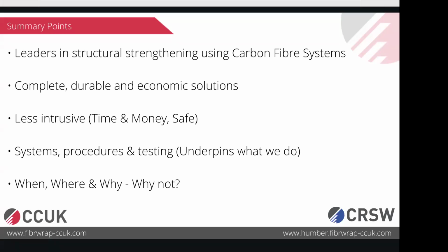The systems, procedures, and the testing. This is what Jayesh has said. If Jay gives my teams or our guys on site a design and it's not applied correctly, then you're going to have a problem. It's absolutely critical that the application process is followed, and this is why none of anything that we do is subcontracted out. It's all kept in-house. Our guys are with us for a minimum of 2 years before they're allowed to apply carbon fiber. And this, hopefully in the UK anyway, is going to be the norm on what we do.